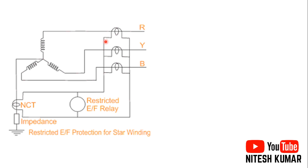So this is the phase CT and here is the neutral CT. You have to connect these phase CTs in parallel, that is, the secondaries of the CTs in parallel. Just consider this is S1 of this CT, this is S2 of this CT. Then this S1 should be connected to the S1 of the Y-phase CT and S2 to S2 of the Y-phase CT. Similarly with the S1 and S2 of the B-phase CT, and the same with the neutral CT also. Then across this parallel connection, the relay will be connected.